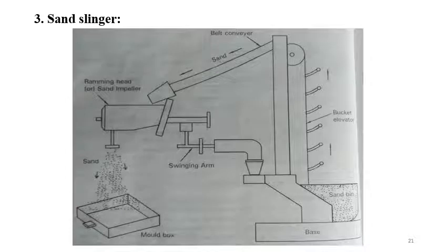Next, the sand slinger. Before the sand slinger machine, manually you took sand and put it into the mold box, and prepared the mold cavity manually. Nowadays, almost all foundries are mechanized. So the sand is taken from the sand storage tank, called a sand bin. Preparation of the sand means we put the additives, binders, water and base sand, mix them in a muller, and prepare the sand.